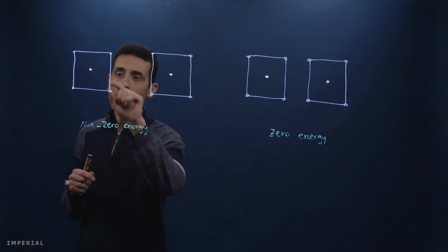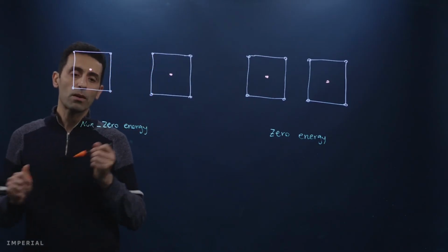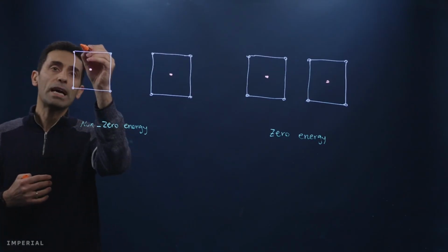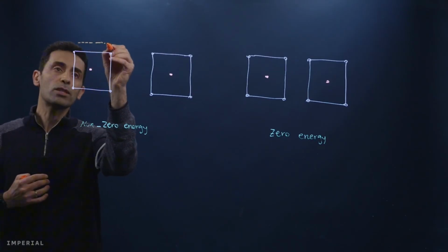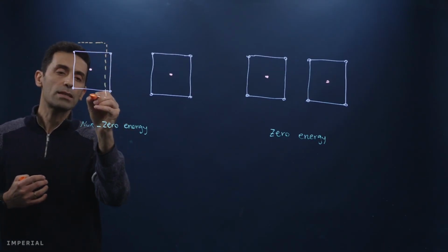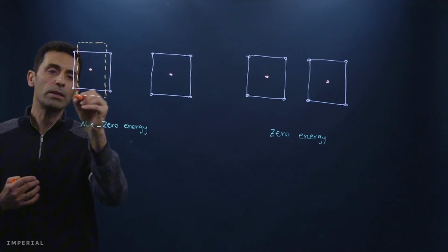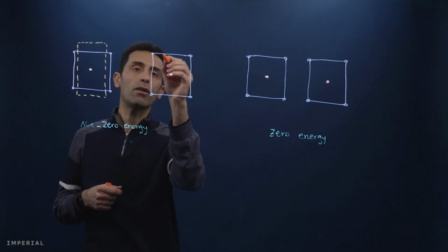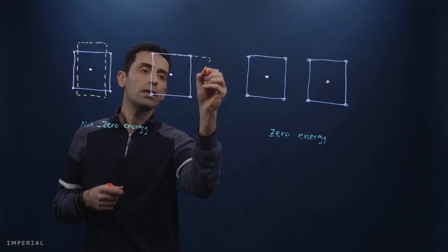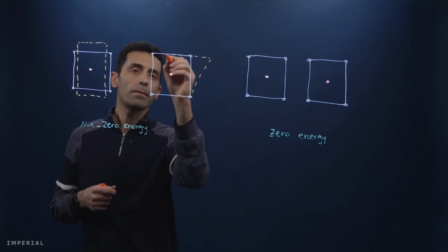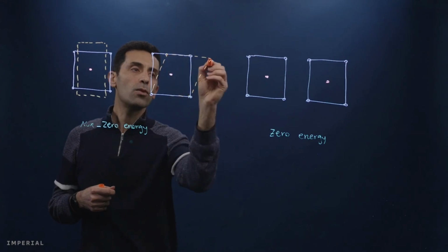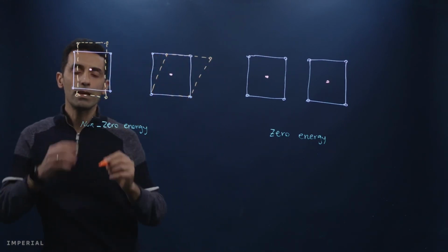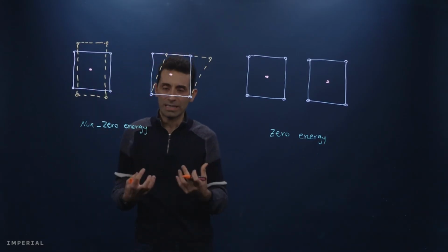First of all, with the single integration, the finite element can sense deformations like this. So you can see this is like stretching our element, or shearing of our element. So it could be this mode. If we have this sort of deformation, single integration can feel it, can understand it.